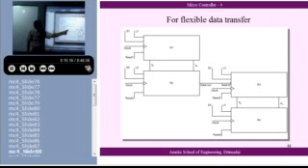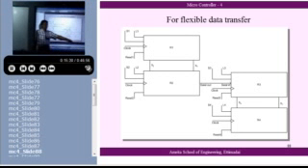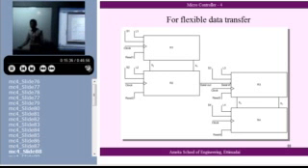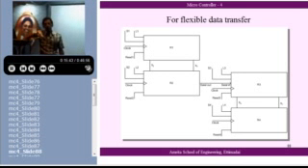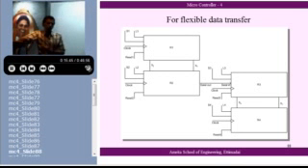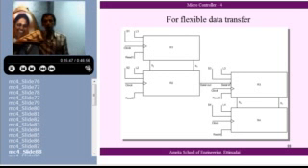This data I can take as serial output and connect to a serial input here. Again give clock pulses. With 8 pulses, this data will go in here serially. After loading this fully, I can take parallel output here and load into this register. So I have taken serial data from here, done some manipulation, brought it to this register. What I am saying is, I have just shown an illustration. I can do a variety of operations: serial input, serial output, parallel loading, one register, another register, different ways I can connect and manipulate them.